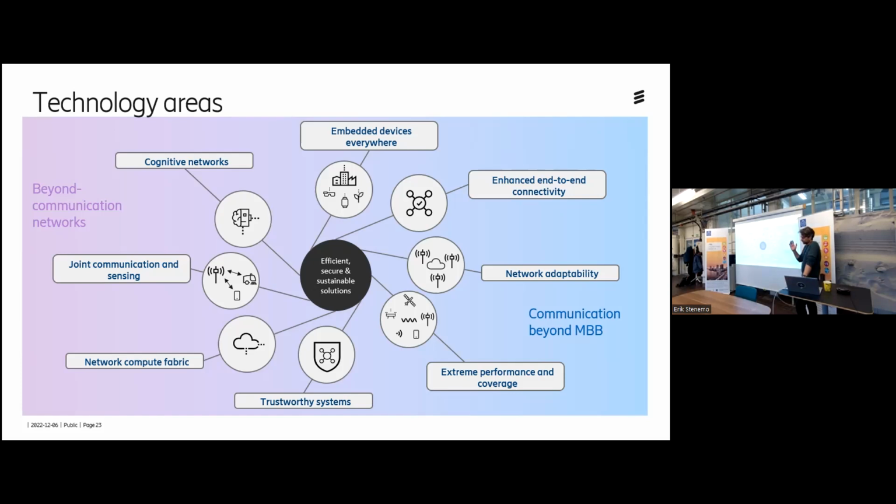So better than to send a specific symbol, so you know that you send a certain probe signal every now and then, and you listen to the reflection of the probe. That's challenging because in principle it would require you to do full duplex. So you would need to be able to transmit and listen at the same time. Otherwise you would be blind in the closest area, right? So if you have to turn off while listening to the echo, you wouldn't be able to see the closest area, right?